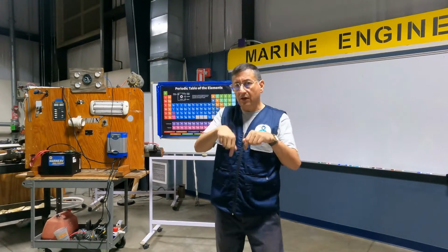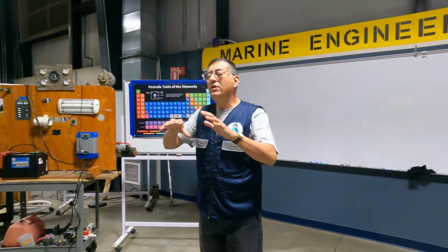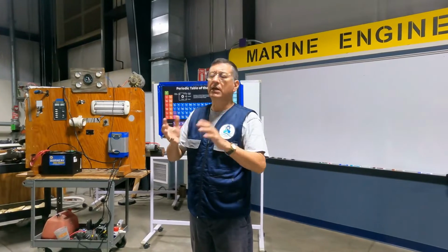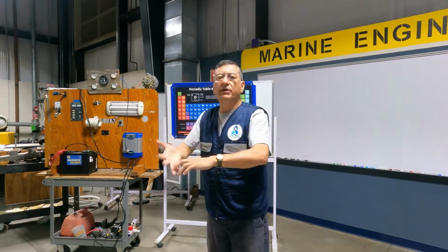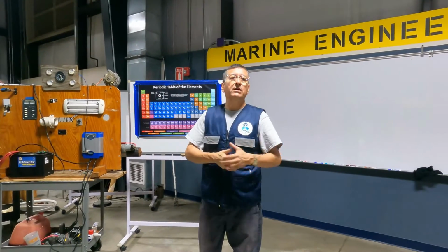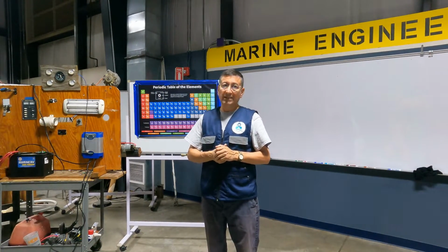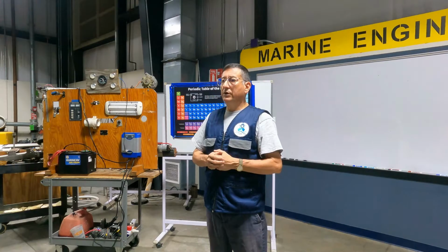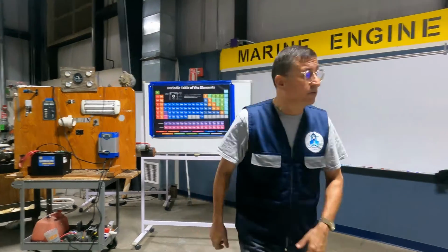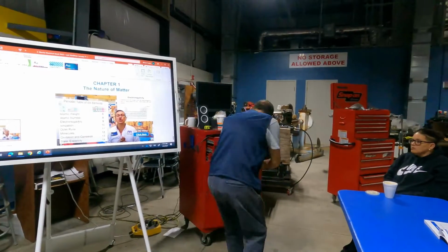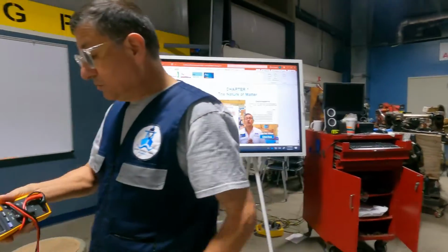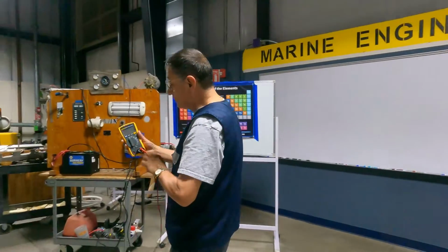In other words, at the end of this class, you are ready to do the wiring in a small boat, DC. Completely, with gauges, oil pressure, temperature, fuel, ignition switch, tachometer, all the gauges. This is DC. This is the first project, okay? And later Danny will explain, we need a good multimeter. This is tool number 1, a good multimeter. I love this brand.